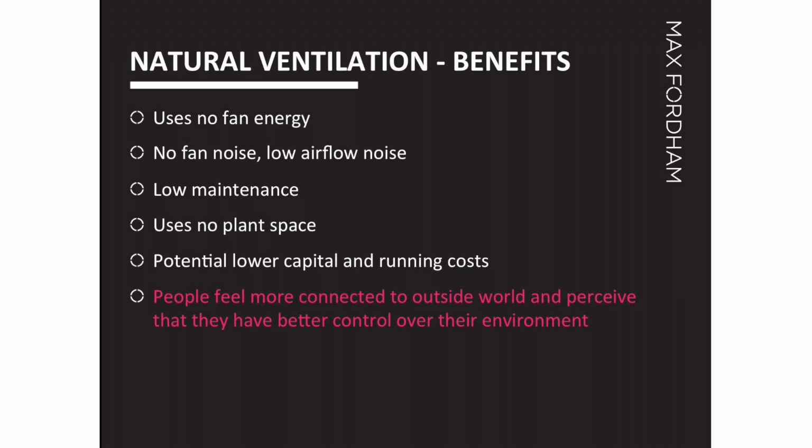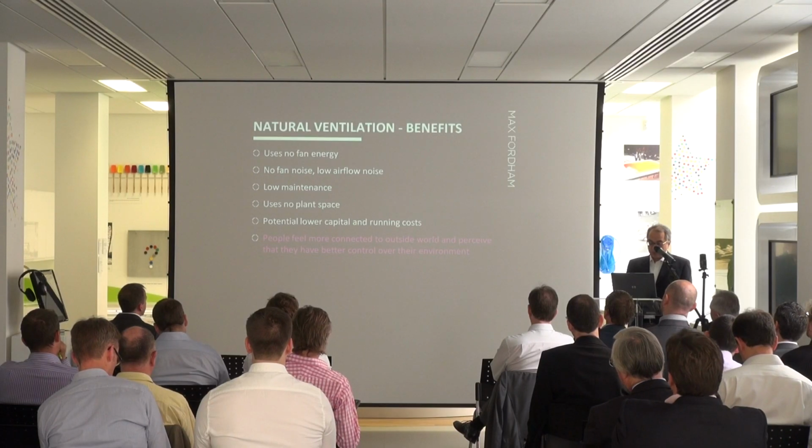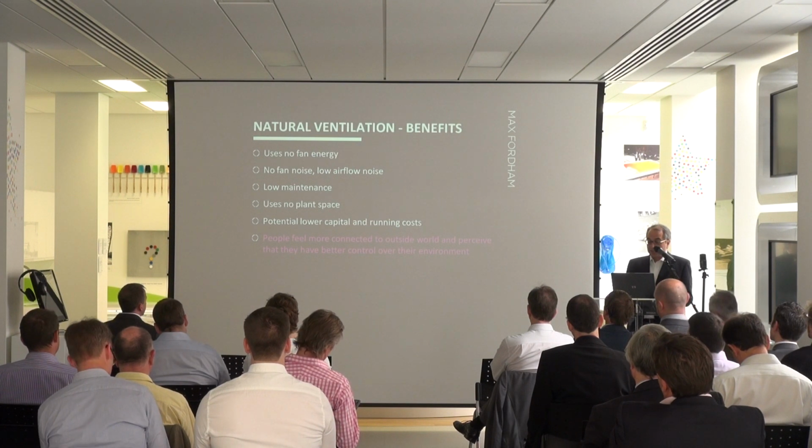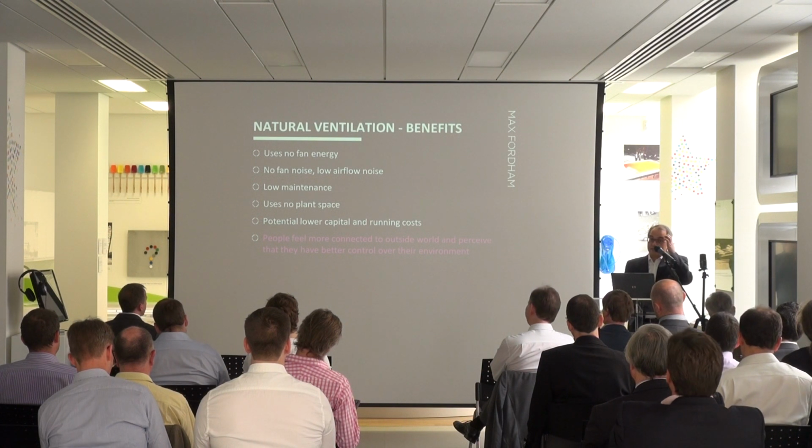So why use natural ventilation? It uses no fan energy, it produces no fan noise, and therefore there's low airflow noise because the air velocity is quite low. It's low maintenance, uses no plant space, and there's potentially lower capital and running costs. And possibly most importantly, people feel more connected to the outside world and perceive that they have better control over their environment if it is a naturally ventilated building.